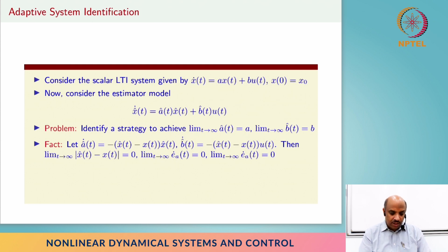The idea behind this entire adaptive control is basically, A and B are constant parameters, but I'm going to start estimating values of A and B through some other function, A hat and B hat. This A hat and B hat are going to be updated constantly, and of course, not surprisingly, they are going to be dependent on the system that we are dealing with.